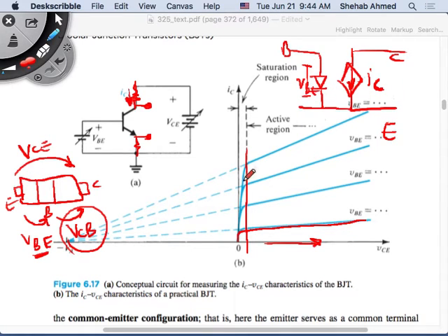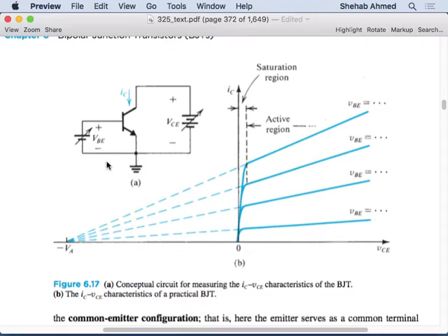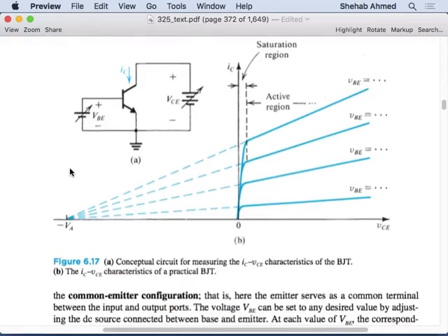If now it's changing, it means that I can model that as a resistor, like we did with the MOSFET. If I put a resistor here, this current flowing through the collector will have to be divided between this and that, which means it's going to affect this slope. So this slope I will represent as this resistor. I'll go through an example where we're increasing VCE, and at some point we'll see that it's not going to be very helpful here.